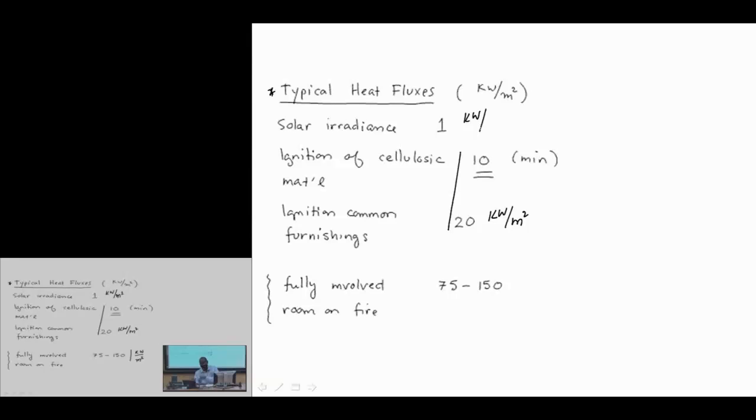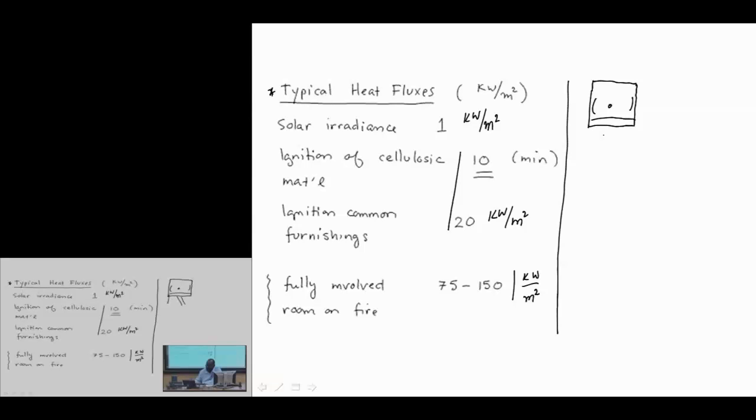Now, these are high heat fluxes, but you have to think about other types of heat fluxes that you might look at in practice. Within an engine, for example, in cylinder in a spark-ignited engine, the heat fluxes that you might get when the flame propagates towards the wall would be on the order of 2.5 megawatt per meter squared.